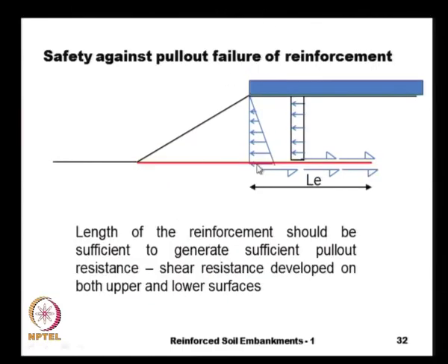And we should also consider the possibility of the provided reinforcement pulling out of the soil, and let us say that the length of the reinforcement beyond this position is Le, and we should make sure that this length Le is sufficient to generate the pull-out resistance against this lateral force with some sufficient factor of safety.